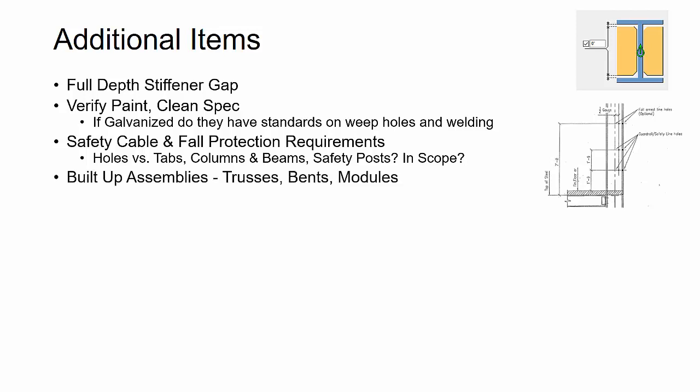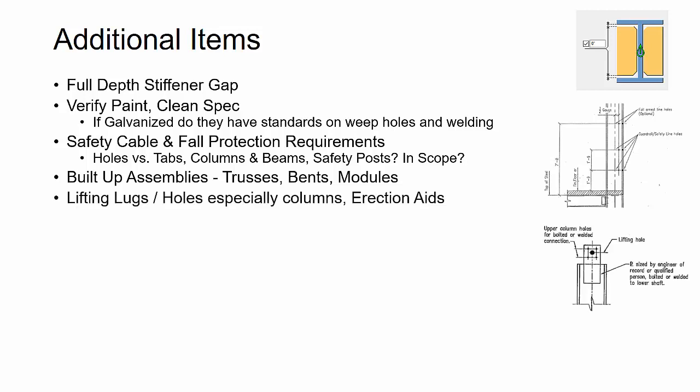Then you're going to want to ask the fabricator and erector about built-up assemblies. If you have trusses on the job, bents, or modules, or even stairs, anything that is more than just a standard beam and column or brace, you're going to want to get direction on, are there splices required? What's shop welded versus field welded? What's the maximum weight or length of an assembly where a splice might need to be required? And you'll want to get clarification on that.